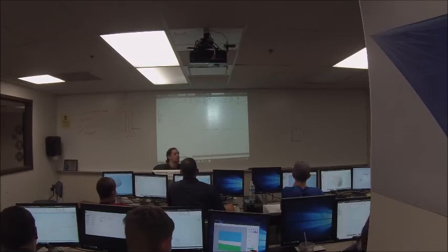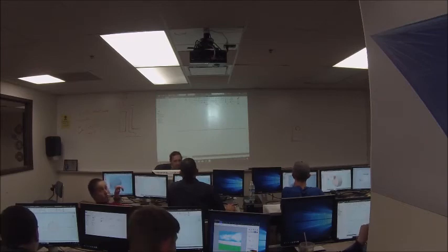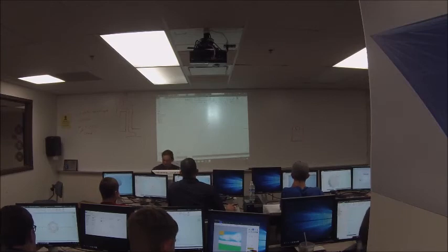If I go too fast and there's something you want me to repeat, just say so. Say the word. I don't want you guys to get lost. I want you to be able to do what you need to do. Okay, so we've got a sketch on the end of this. Create a circle that's smaller than the bigger circle, however big you made it. I'm going to make mine 1 inch, and then finish the sketch. So you guys should have what I have on my screen, right?